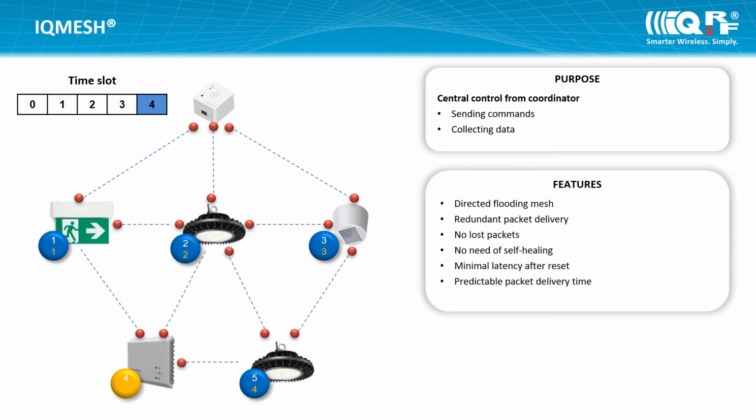You can see the redundant packet delivery on every routing node. And finally, the other C has received the packet 3 times in different time slots. The time slot length depends on the RF mode and the packet length, and it is from 40 to 100 milliseconds.